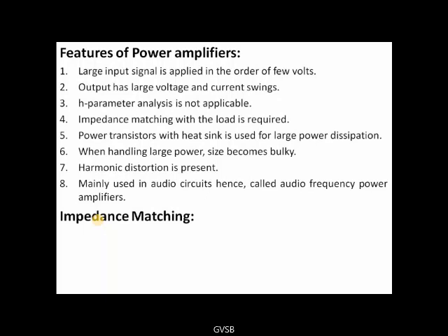Why is impedance matching required? We already discussed it. In order to deliver more power to the load, the output impedance of an amplifier must be matched with the input impedance of the load. Then only the power developed in the amplifier will be transferred to the load.